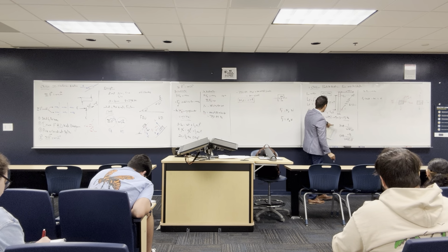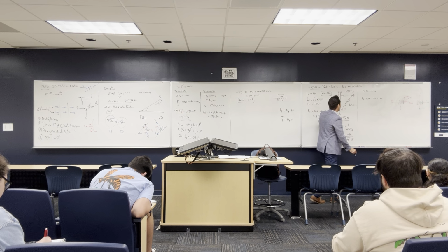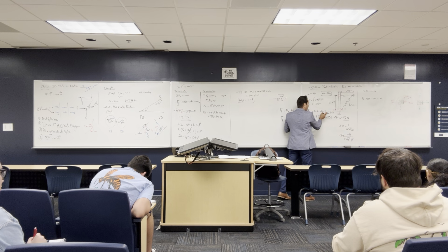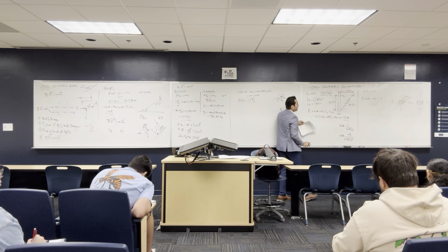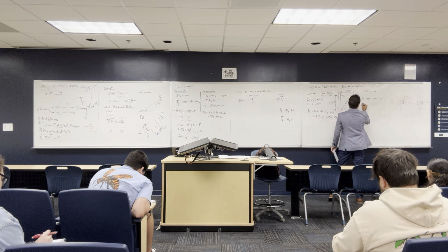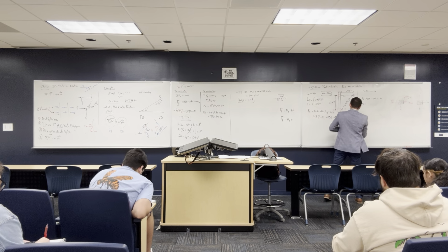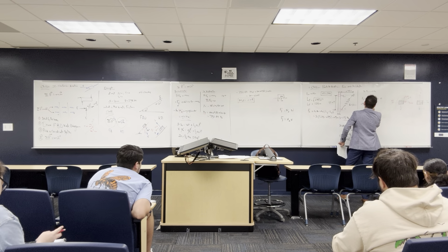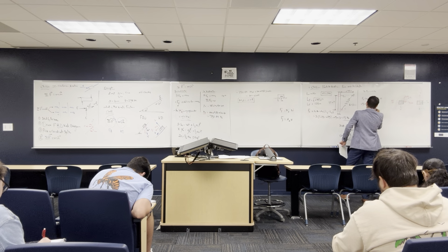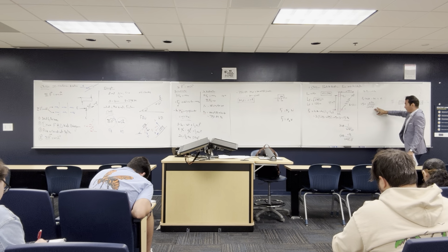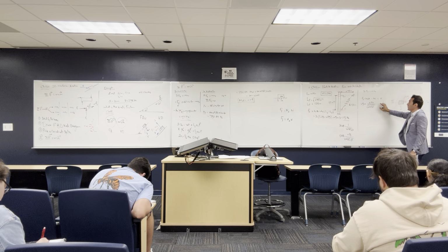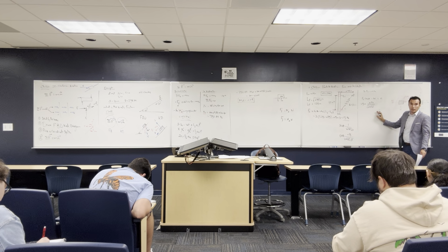Okay, F spring we just got here, 1.5 newtons. We got the delta, which is L final minus L naught, multiplied by K, and we got the force in the spring. It's equal to 1.5. And cosine theta we just put here, which is 0.75 over the root of 0.75 squared plus 1. You can calculate this value right away and substitute it here, but I would rather do it in the final equation because there was a lot of approximation here.